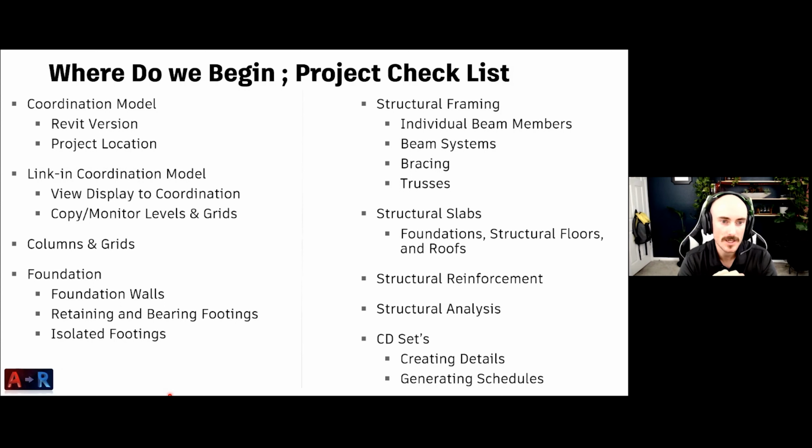Also, project location. Usually as the structural design team, the project location is already set up when we link in a coordinated model. We don't really have to do too much more to move forward. But if there is something that needs to be talked about, it should be happening in that coordination meeting. And then when we link in the coordination model, we can start off. Linking in our coordination model, we talked about links. They almost correlate with XREFs.